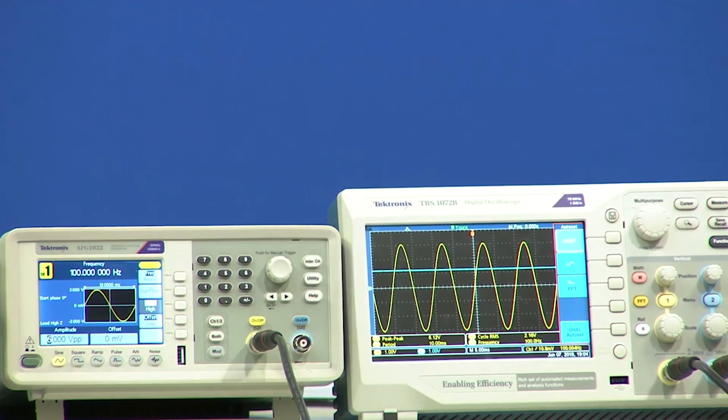Now what is the other stage that we have seen? The other stage is that we have to pass through the comparator. So we have to connect the negative input of an op amp to this particular point and the positive input to the input signal, so that with that connection, we can see the output of the op amp go to the plus VCC state whenever the input is greater than the threshold.